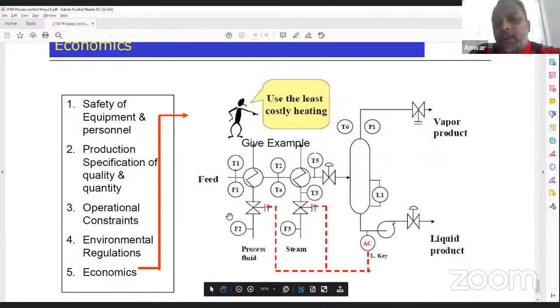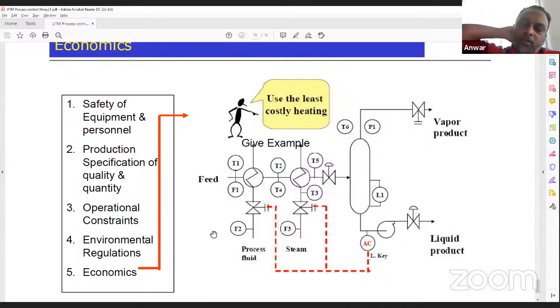So you have a heat network analysis in the plant to see if you have any energy that is being wasted that you can recover, so that you can reduce the use of direct heating from either electricity or natural gas by producing more steam.